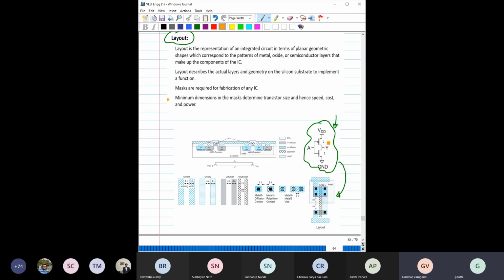So just to give you an idea, here you can see the PMOS width is 2, NMOS width is 1, because we know the mobility of electron is 2 times that of hole. So to make the resistance of both pull up and pull down network equal, we have to make the width 2 times. So you can clearly see, this is actually PMOS. This is the tap part, where this is for the contact part. This is the polysilicon part, right? This is the polysilicon gate.